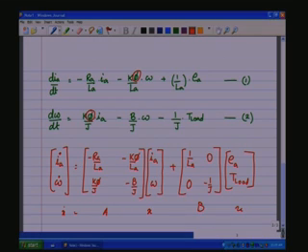Now, if phi is not a shunt, but let us say a series motor, in that case phi itself is a function of IA. Which means here phi becomes proportional to IA, which results in, let us say, this becoming K1 IA.